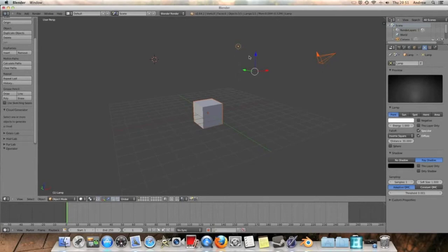Yellow meaning that it's the main object that we're looking at, and the other ones are just part of the selection, which will become clearer when you get around to it later, but that's basically what that does. But it means we've got this main one selected, and if we actually press Shift and right click it again, the yellow one, it'll deselect it.